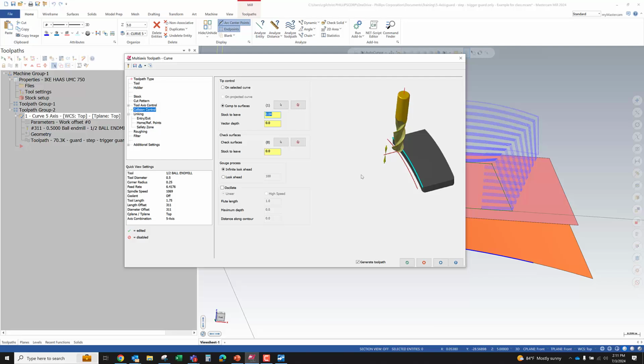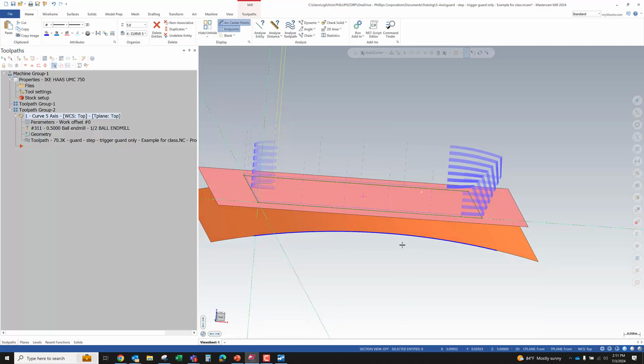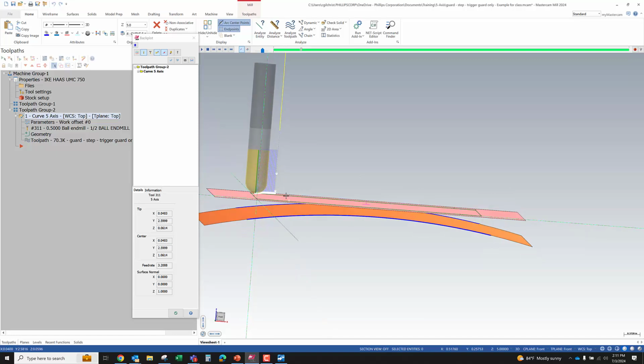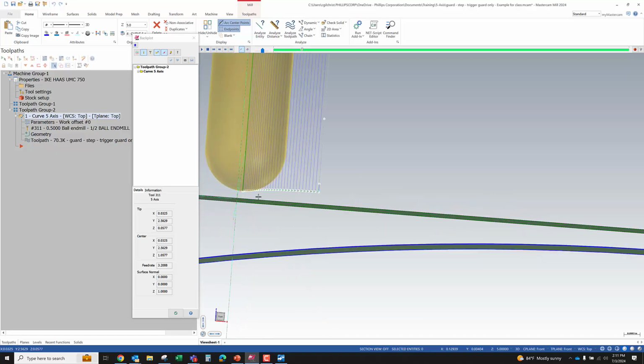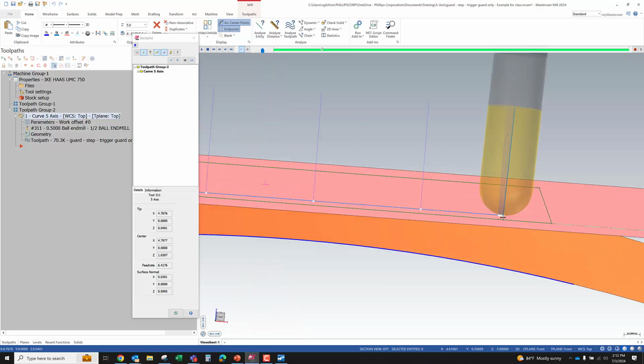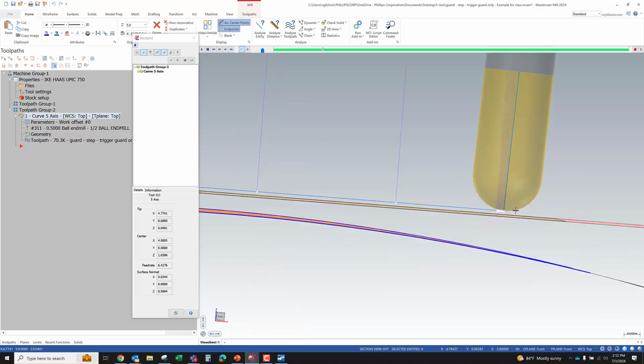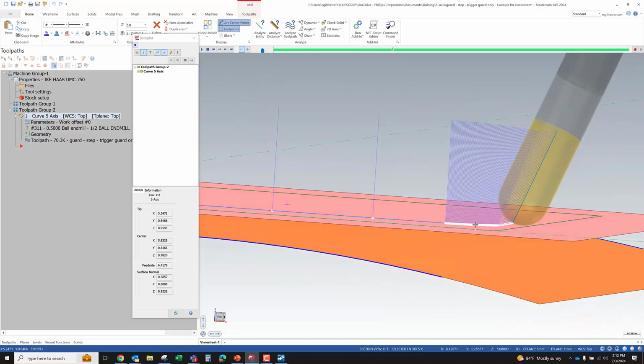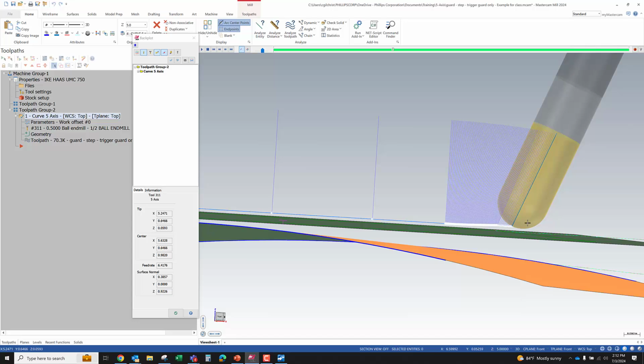So let's say, hey, we're going to leave a millimeter. We're going to leave 40 thousandths of an inch. Now, all we did was take the whole toolpath and say, everywhere that you're driving, I want a little bit of stock to leave. And whether it's vector depth or stock to leave, the tangent point of our ball should be staying exactly the same height above, even though the center line of the vectors is raising, the plane of tangency is even.